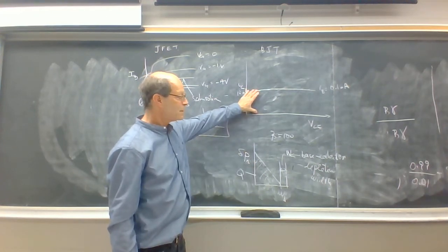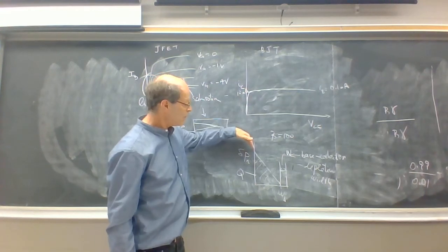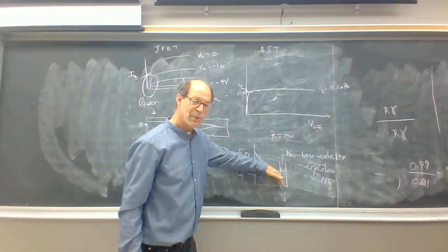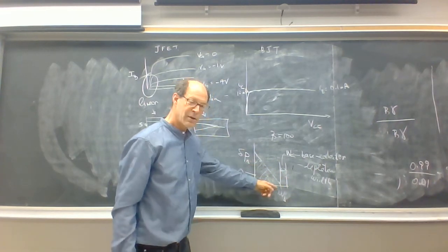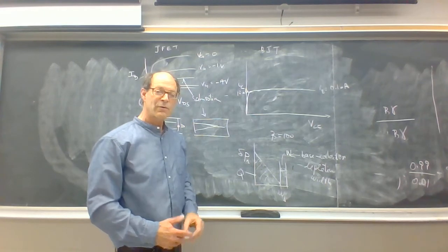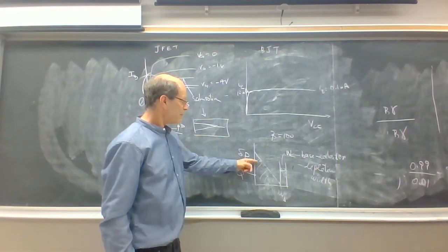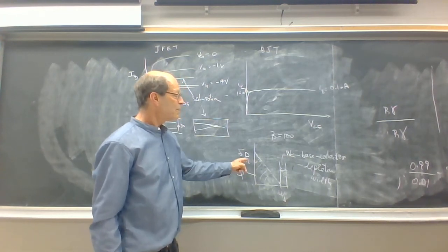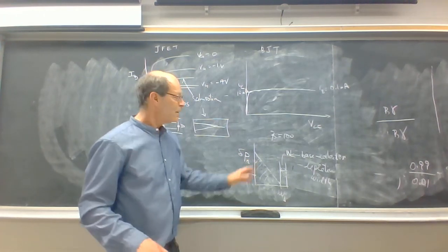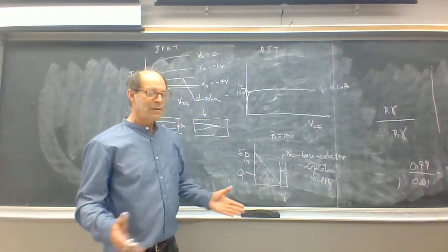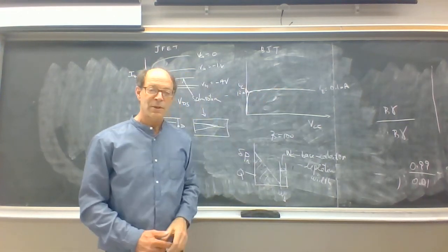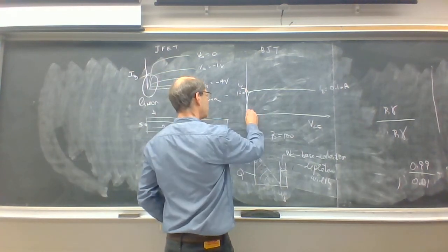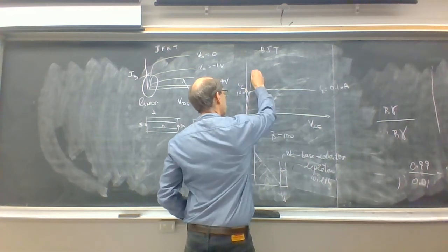That condition exists because the current flowing into the collector is determined by the slope. And the slope of this excess carrier concentration in the base is controlled by the emitter base junction. If the emitter base junction is not affected by the collector emitter voltage, then this current would just remain relatively saturated. So now if I want to change that current, I could go to a different base current.